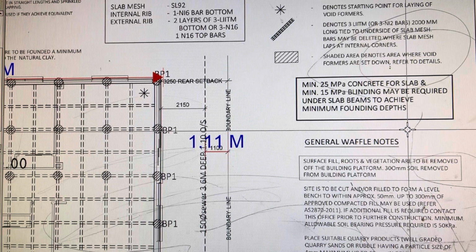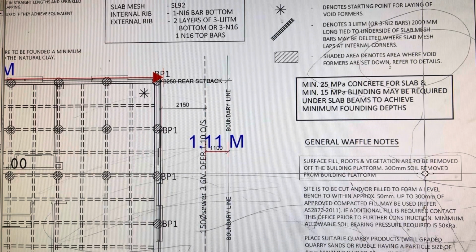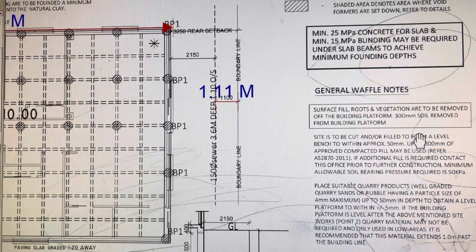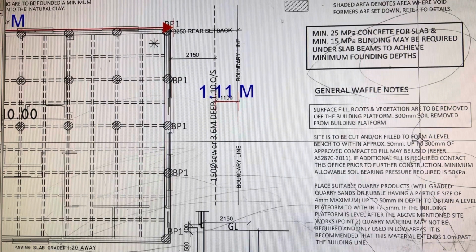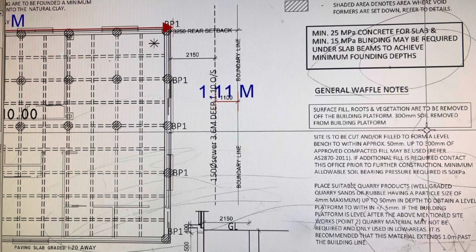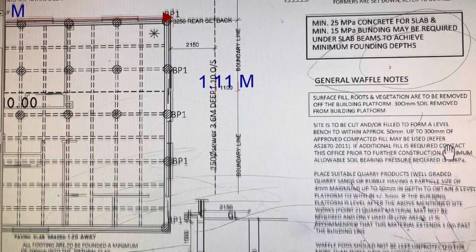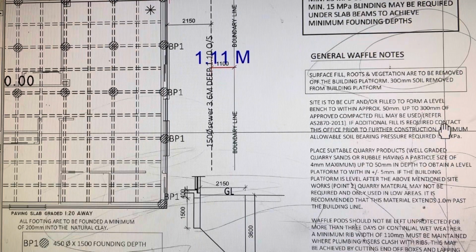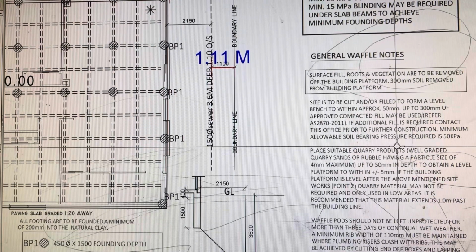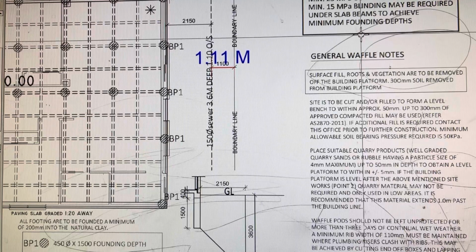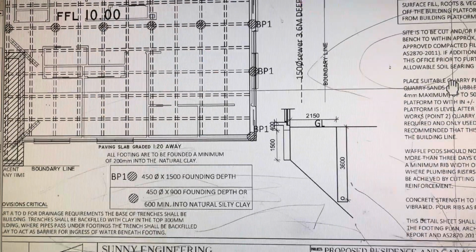Blinding concrete goes under the main footings. If the soil is very loose and you have to reach say 100 kPa strength of the soil, then you have to dig till you reach that 100 kPa strength of the soil. Or in this case, you may have to go very deep, and then that depth you can fill with blinding concrete and then your normal footings.